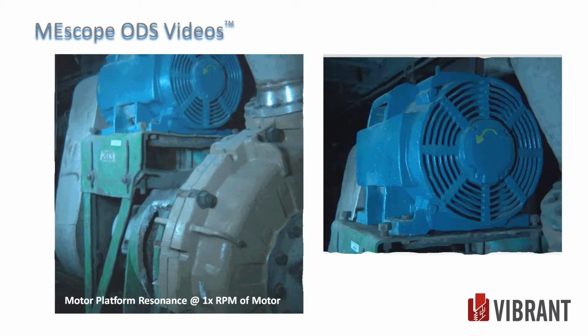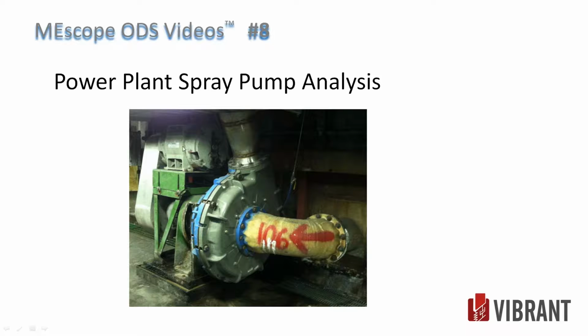Oh, design of the structure. It's a belt-driven fan or belt-driven pump. This platform has given them all kinds of problems. So for every driving force, we have two different shaft speeds. We have pump speed, we have motor speed, we have belt frequency from the pulley system, and the multiples of all of those that are exciting natural frequencies in this frame. Not a great design.